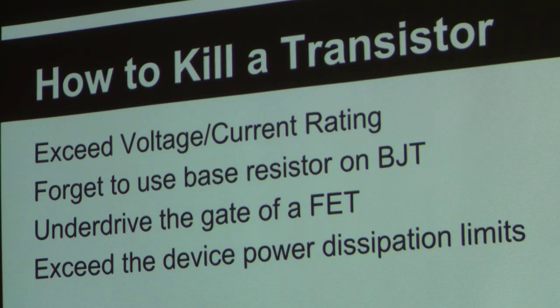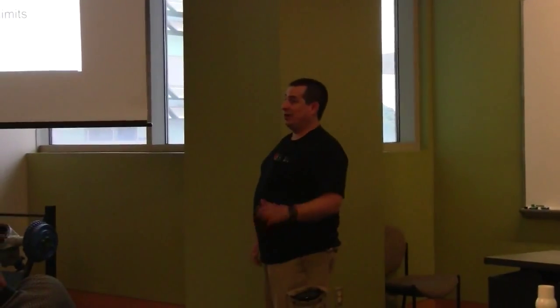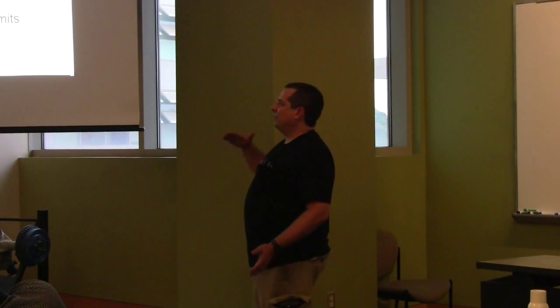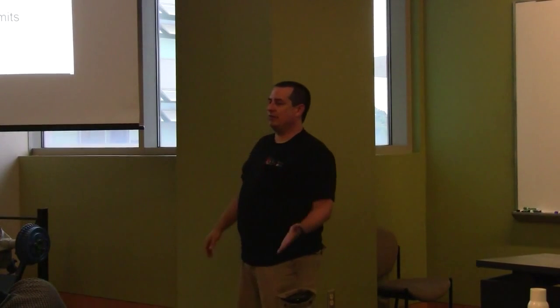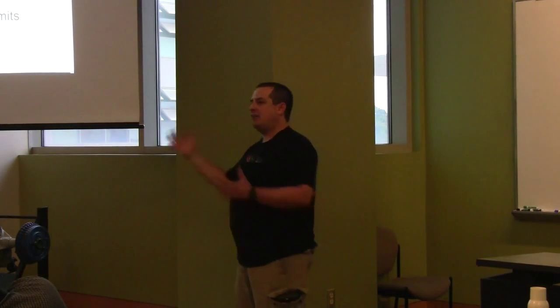Why does that crap it out? Because what happens is the FETs fall into a whole range of categories of how sensitive their gate voltages are. Generally, the limit is don't go above 15 or 20 volts. But some may take 10 volts to turn on, some may only take 5 volts, some may only take 3.3 or 2.5. I was using one that needed 10, and I was driving it with 5. So it was turning it halfway on.